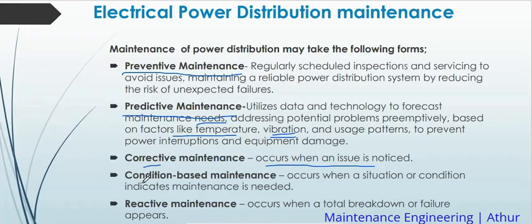And all those people that are supplied by that phase, maybe sometimes they start dimming, okay? But others are working well. So that is a situation or a condition, people are complaining that they have dim light. Then as a team, you have to come and know why. If the phase is overloaded, then you remove some customers and put them on the other phase.